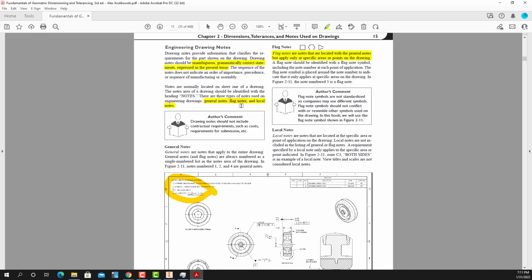And I'm going to have the whole assembly, and it's going to have its own part number that's going to be stamped, let's say. You always want to put your part marking where it's going to assemble to something else and get covered up. Because then they can stamp the assembly here. And it's not that part. So if I have my part number right up here, and my assembly over here, well, which one is it?